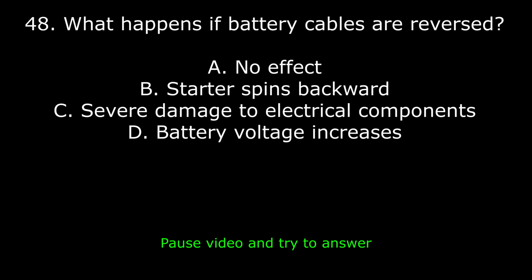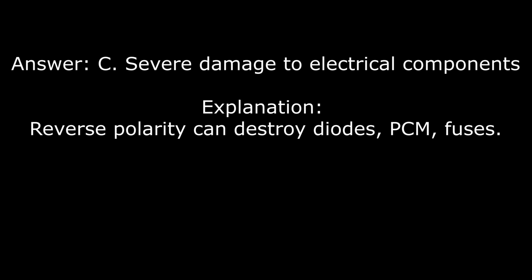48. What happens if battery cables are reversed? A, no effect. B, starter spins backward. C, severe damage to electrical components. D, battery voltage increases. Answer: C, severe damage to electrical components. Explanation: reverse polarity can destroy diodes, PCM, fuses.